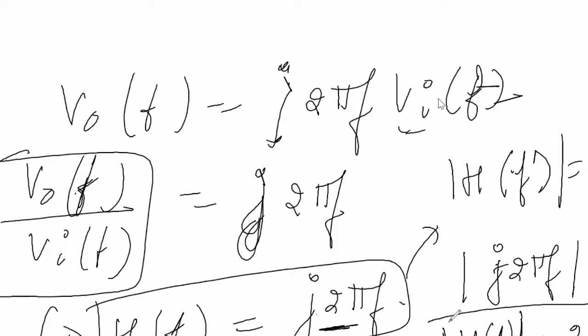So what is the implication of this expression? This is an important expression which is useful to us. If you take the magnitude of any transfer function, it gives you the amplitude of that function. So we find from this expression that amplitude has become proportional to the frequency.